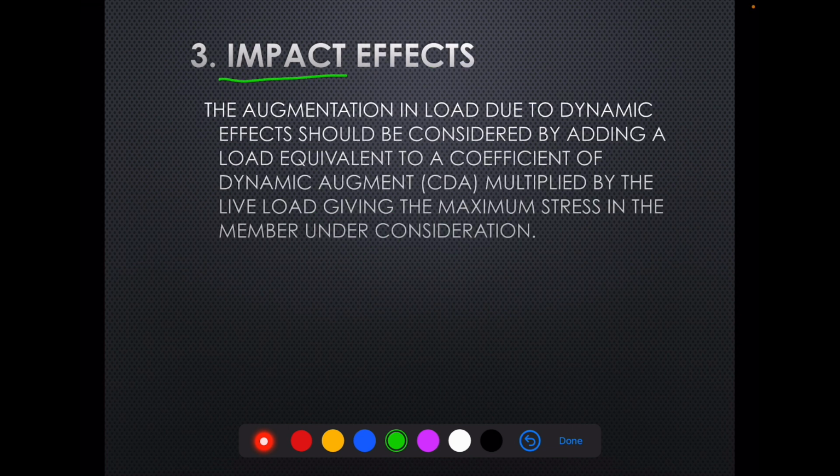Then we have impact effects. The augmentation in load due to dynamic effects should be considered by adding a load equivalent to a coefficient of dynamic augment, that is CDA, multiplied by the live load, giving the maximum stress in the member under consideration.